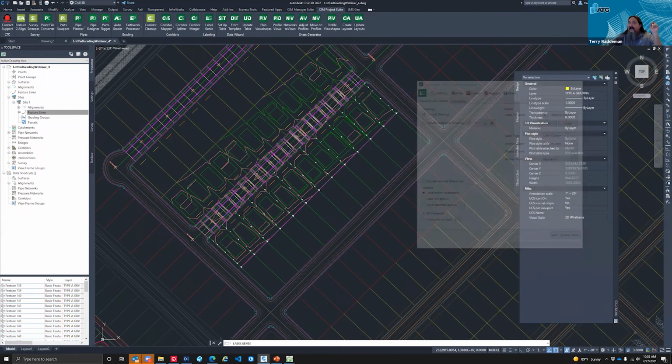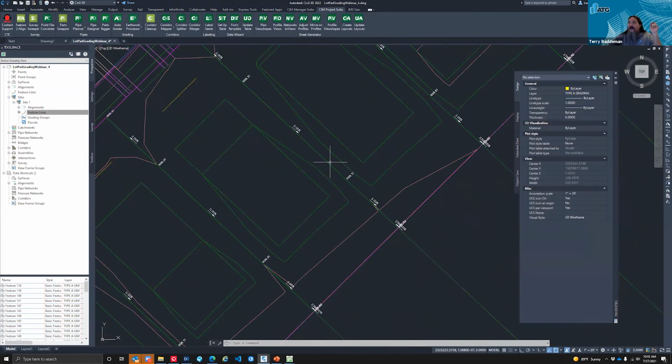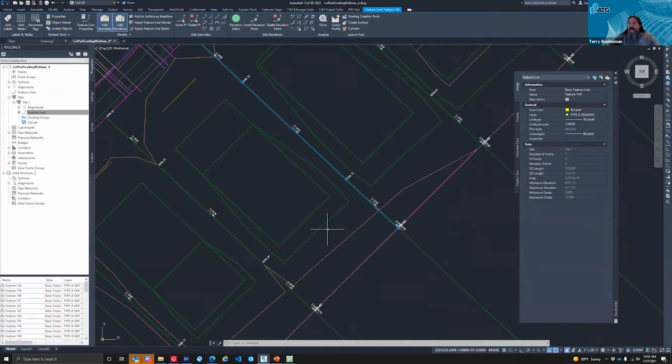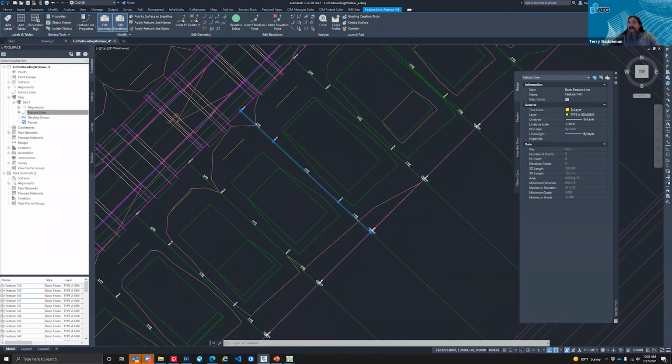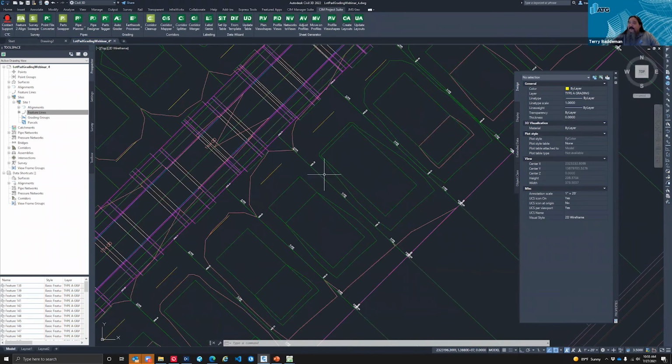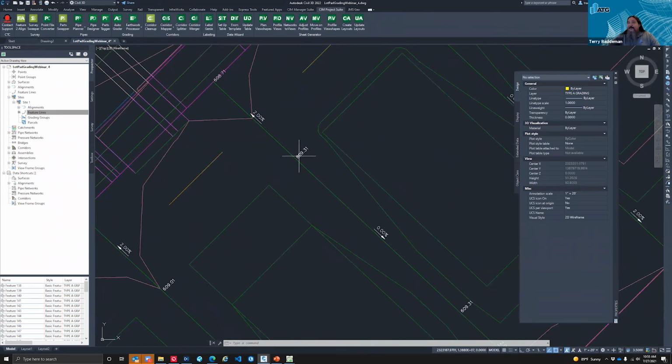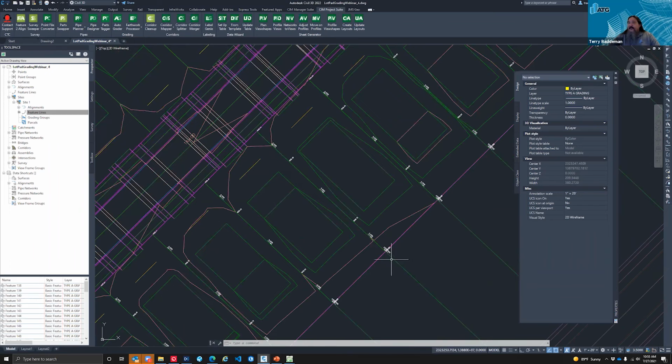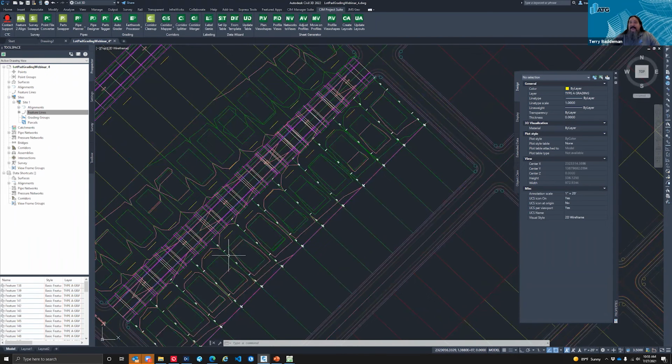I'm going to go ahead and click OK on that, and I'm going to zoom down here, and I specified my lot layer. It's using lot A. It didn't do lot B because I didn't set this up after I did it. So it's doing it on lot A. Every vertex that it finds, it's putting an elevation point, and then between those, it's adding a slope to it. So instantly, instead of going through and clicking 54 times on my drawing here, I can use Label Genie to place all these labels according to what function or feature or style that I'm using and apply it to that object.